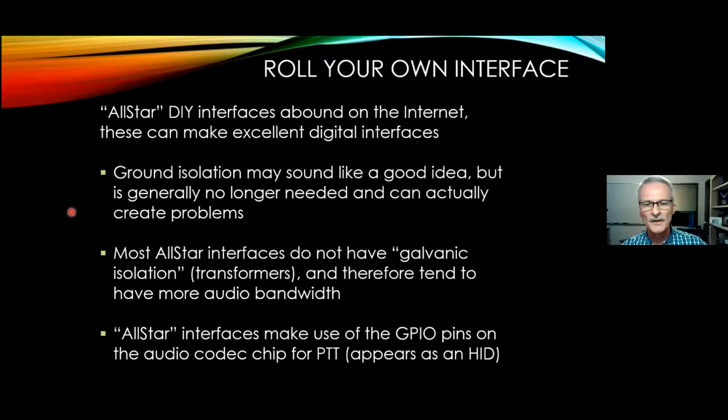The transformers that were in the older Signal Links just didn't have the audio bandwidth to get really good high-speed performance out of them. They've now switched to newer transformers, which are even smaller, and they think those are going to perform better. I don't see how that's possible.